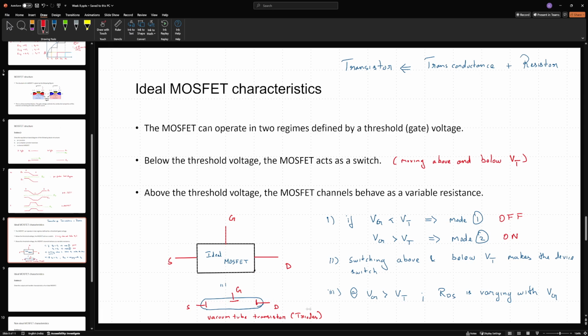So that is the whole essence that I want to convey here, that for transistors of every kind, FETs or even BJTs, the idea is to first understand what kind of device characteristic and property I want. And then, based on whatever we know about the materials, we should try to construct devices which can exhibit those properties. So a very integral part of the knowledge that we need to acquire while dealing with subjects like these is to treat the devices as systems. Start with something as simple as a PN junction diode. It's a device that allows current flow in one direction and blocks current flow in the opposite direction. That is all I want.